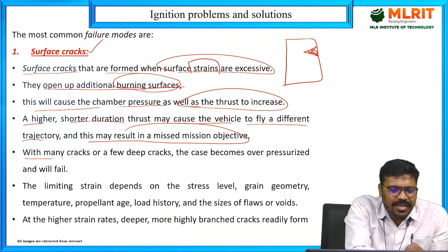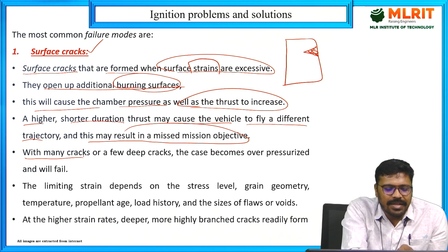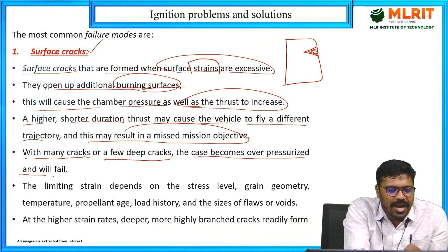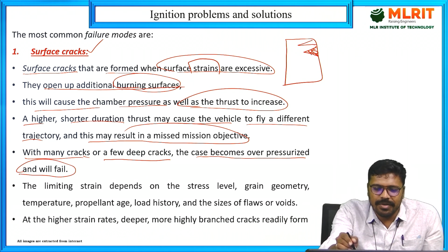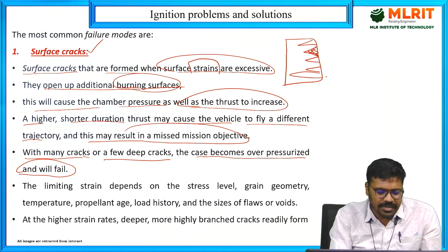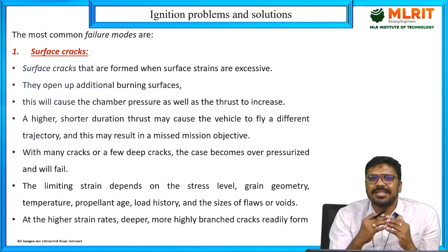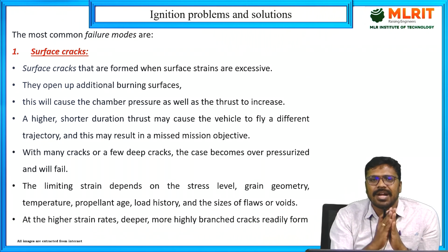If the cracks increase, with many cracks or a few deep cracks, the case becomes overpressurized and also fails. If more cracks are formed, and the cracks are deeper, then there is a huge change in the chamber pressure. If the chamber pressure exceeds the limit of the motor case, then there is a chance of complete failure of the motor case.